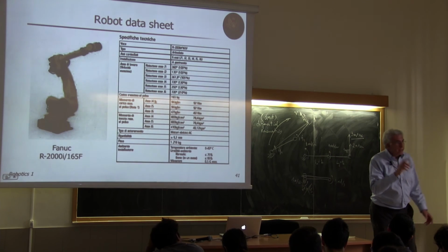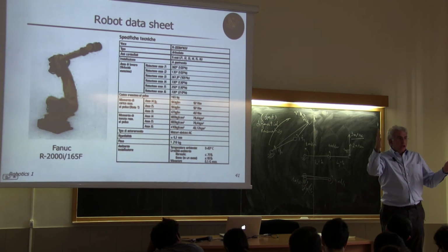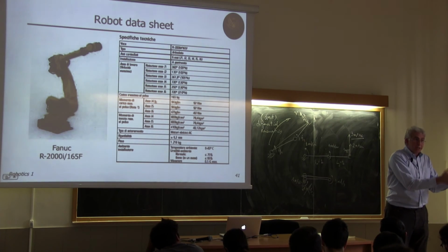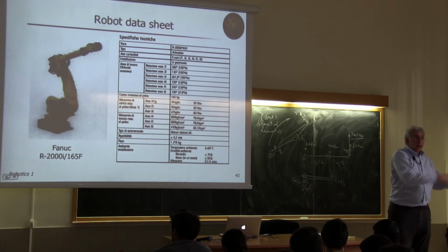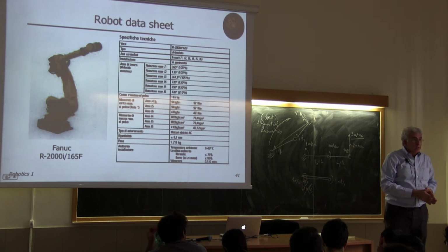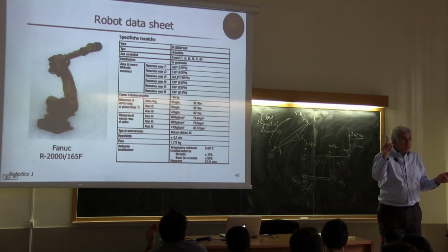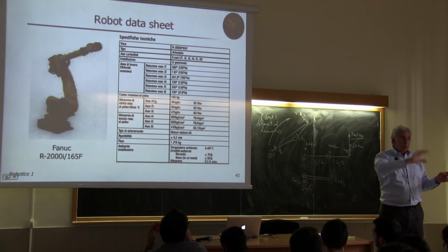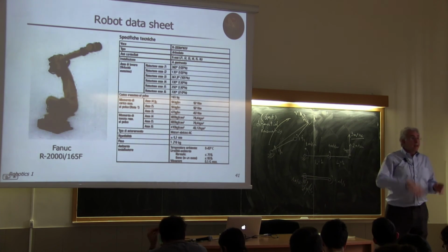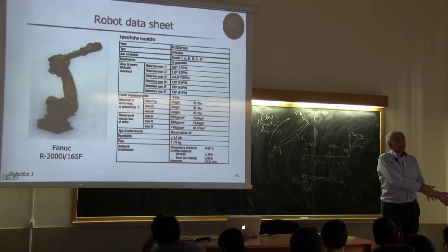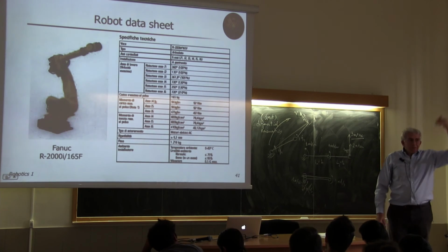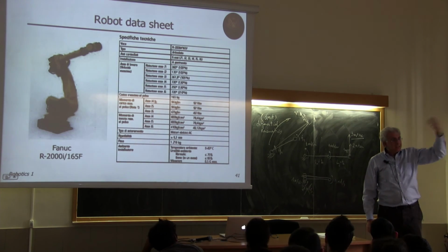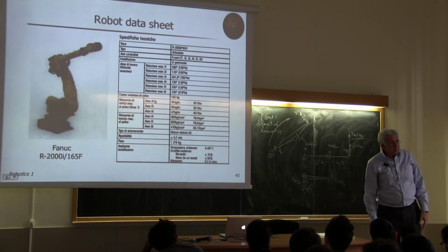So, in fact, if you have a robot with n joints, you have n plus 1 bodies. The base body 0, which is not moving, and the n bodies which are moving, one each after the associated joint. So we will have n plus 1 frames, and we will characterize the relative position of these n moving frames with respect to the 0th frame, which is at the base. Okay, this is forward-looking toward a systematic way of describing kinematics. Okay?